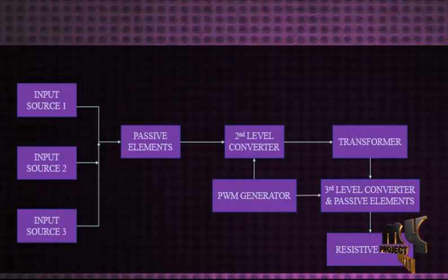Generally, the proposed multi-input converter is essentially based on the operation of the 3-level isolated DC to DC converter. The secondary side rectifier can be either a half-bridge rectifier accompanied by a tapped winding for low output voltage applications. Since the PWM scheme here is very similar to that in 3-level converters, the control complexity is not intensive.